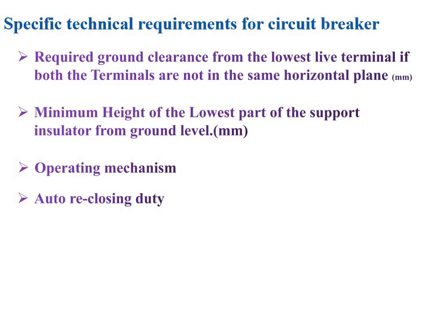Then next is the rated operating duty cycle. Here you have to mention open, then close, then open, then again close, then open. Between these you have to decide the time. Means once the circuit breaker is open and you have to go for the single auto reclose, before closing the contacts you have to wait for some time, and that time is generally 0.3 seconds.